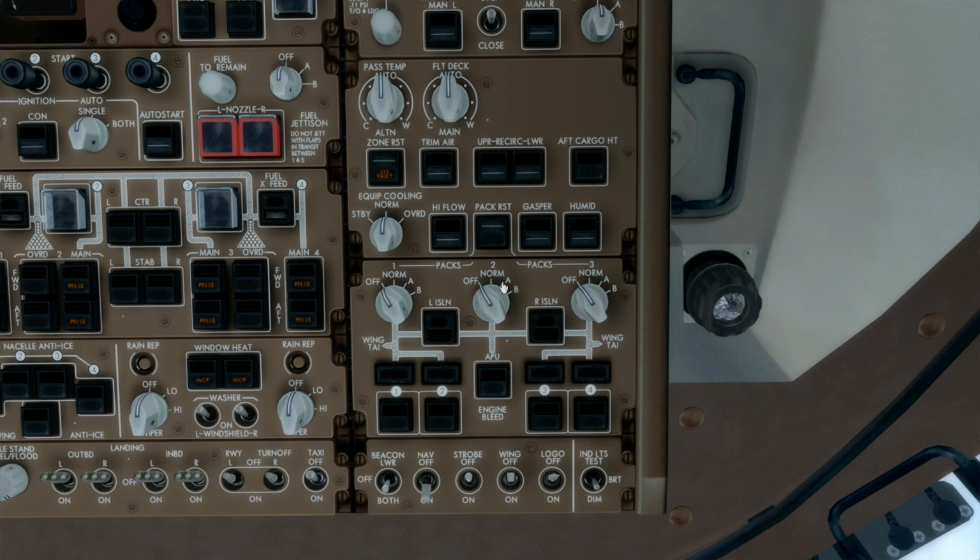There are 2 pack controllers, A and B. In the norm position, they are alternated automatically from one flight to the next. Redundancy, yay! But each pack can be set to use a specific pack controller if desired. If that particular pack controller malfunctions, then the other one is automatically selected, overriding the choice on the switch.